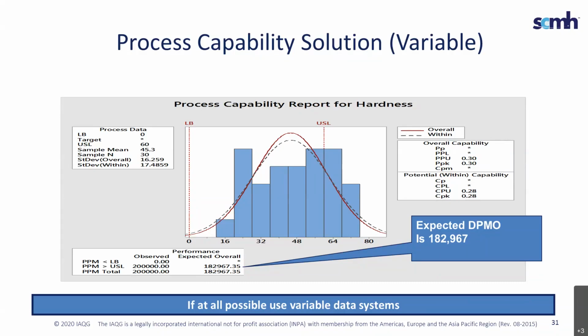Again, processes like that are very common. You can't center it, but you should always be shooting for having that correct level of CpK that you're shooting for. 1.33, 1.66, 2.0, 1.0. So that way you are away from the spec limit. And it's okay not to be centered.